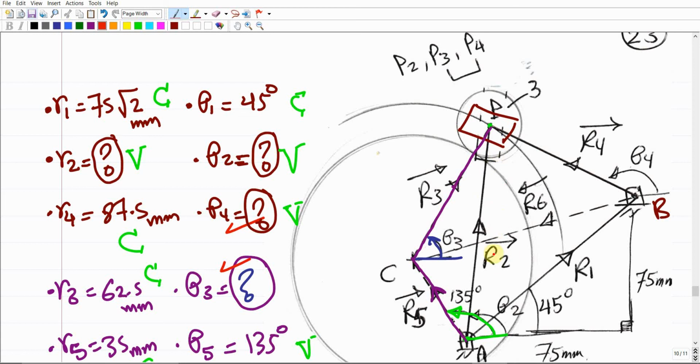And this explains why R2 is going to increase or decrease. It means that there is a sliding velocity of a virtual slider with respect to this point B. It means that we do have two different sliders. One is parallel to the R2 and one is perpendicular to the R2. Like this is the normal or radial direction, and this is like the tangential component over this curve.